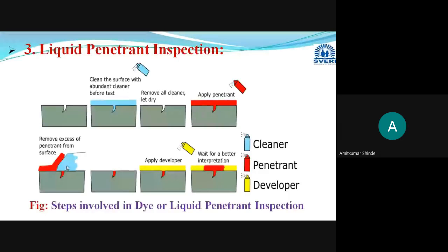Okay, this is the penetrant removed. First is cleaning, drying, application of the penetrant. Then fourth is removing the excess penetrant. Now the removal of this excess penetrant can be done with the help of cotton paper. You can use that cotton paper and remove the excess penetrant from that surface, and this type of surface will be obtained. So first stage cleaning, drying, application of penetrant, and removal of the excess penetrant with the help of soft and clean cotton paper.